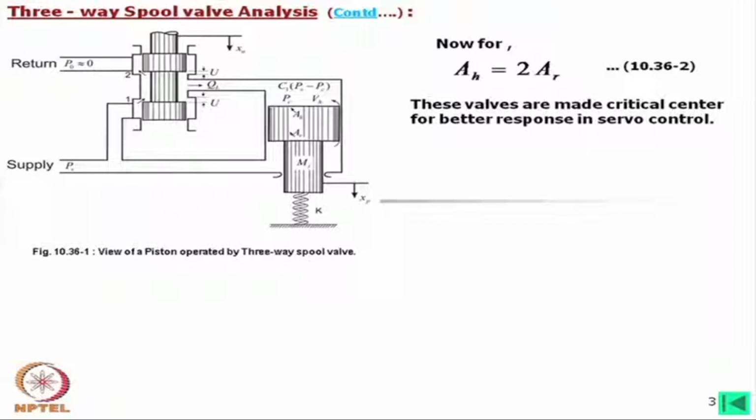Now, adjustment with the solenoid positions and these spool positions, because the solenoid is not directly coupled, it will be directly coupled, but not a single component. The solenoid spool and this spool are not an integral part, they are just connected. So, sometimes it deviates from these critical center positions, and that can be adjusted, of course.